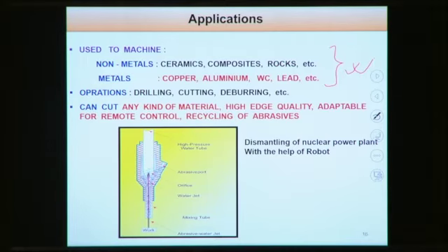Because the water jet is coming, the water inhibits the formation of heat. Whatever heat is generated is taken away. So there is no fire hazard in abrasive water jet machining. What operations can be done? Operations like drilling, cutting, and deburring can be done by this process.